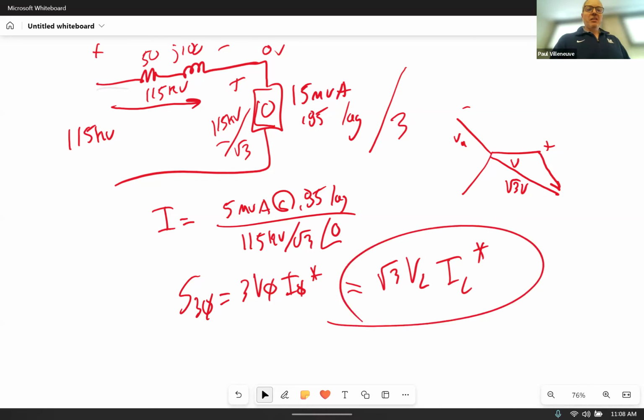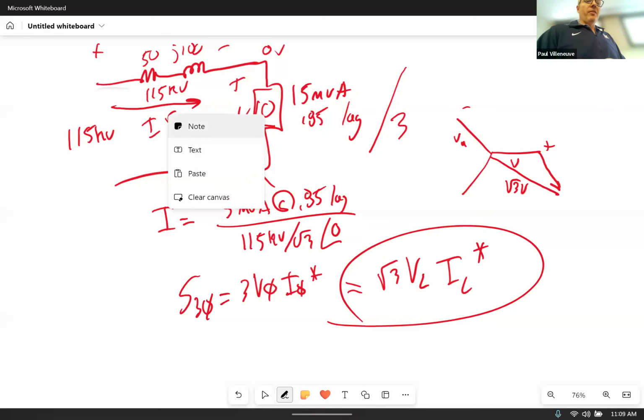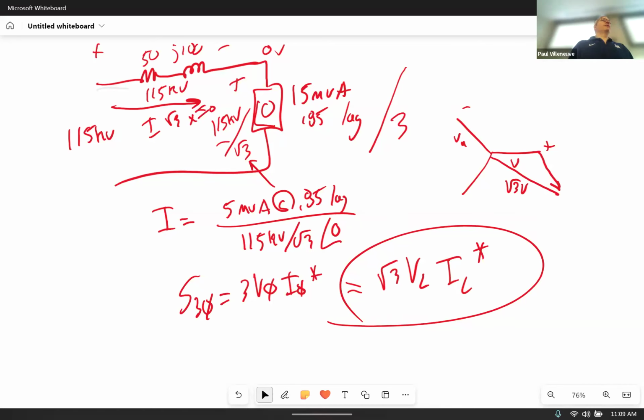By using this equation, and then just saying, let's just divide the voltage by the square root of 3, I've included the fact that whatever current that I'm going to calculate has already had that square root of 3 divided out. So it just massively simplifies what it is by just putting it on the voltage. You could have had a delta, but then we'd have to go ahead and say, oh, well, the current over here is going to be the square root of 3 times the phase current. So you would have had to do it at that point anyway.